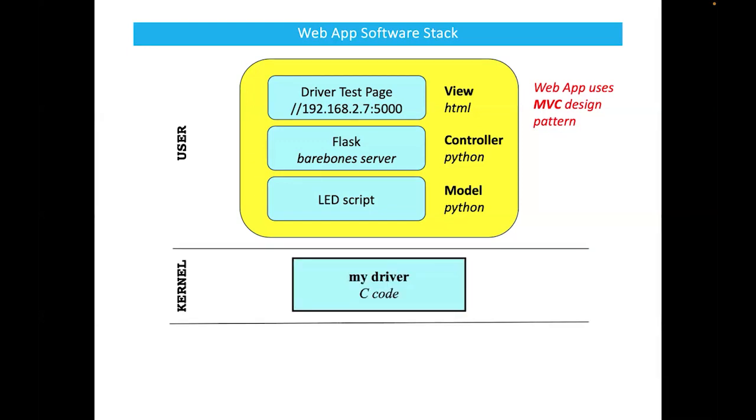In the kernel itself, we're going to load a driver. So that's something that we've written. And this driver can basically drive GPIO pins, and it can also handle interrupts. So this runs in kernel mode. And then that directly controls the GPIO registers in the Raspberry Pi 4. So that's the basic stack. So the idea was to develop that sort of stack and then use that as a basis for further development later on, just to get all that working, really.